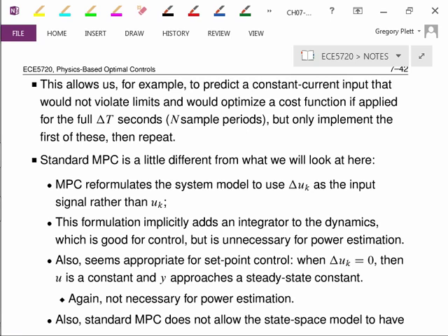Now, the most important part of model predictive control versus other types of control is that built into the methodology is the ability to handle hard constraints. The thou shalt nots: thou shalt not cause lithium plating to happen, thou shalt not cause lithium depletion to happen in different places of the cell.